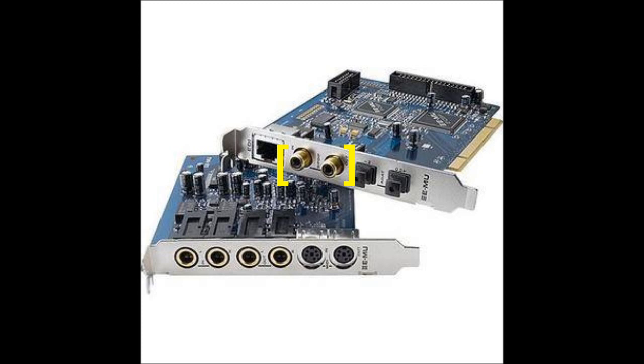Some manufacturers call this a Dolby Digital Interface, and it has to be an RCA coaxial with an impedance of 75 ohms. If you use regular audio RCA cables, you may not have the desired performance that you are expecting. This cable transmits and receives digital data to and from any external digital source without converting digital to analog.